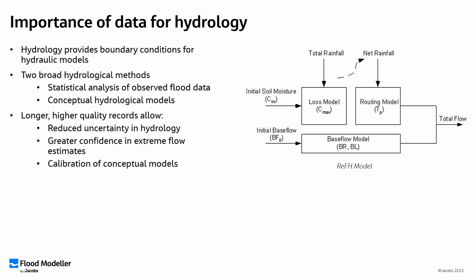The long-term data also lets us calibrate conceptual models. So you can take observed data, put it into your conceptual model, and see how well it performs using observed rainfall and comparing that to observed flow. So really, the more data you've got, the more confidence you'll have.